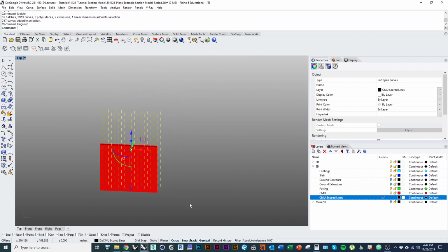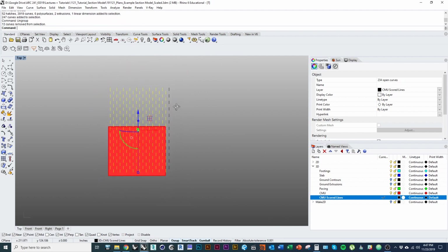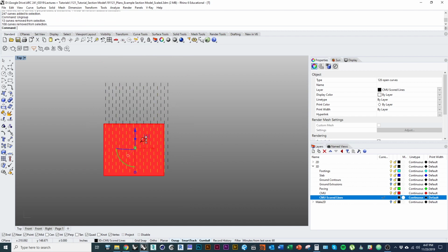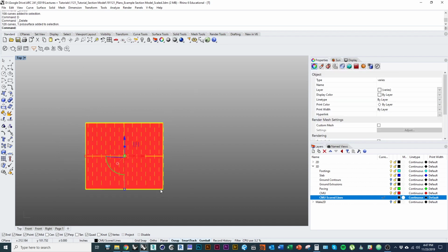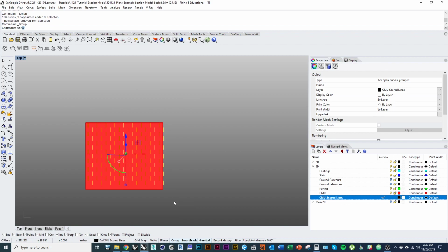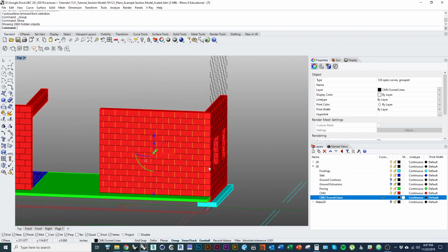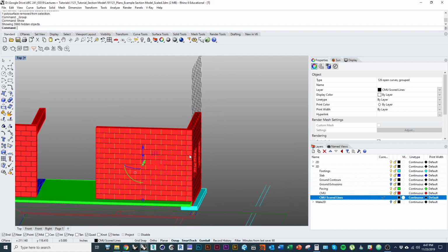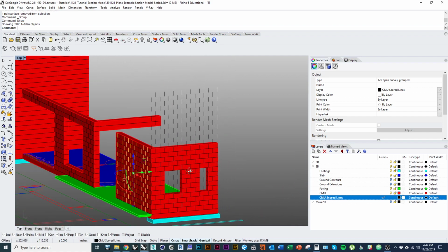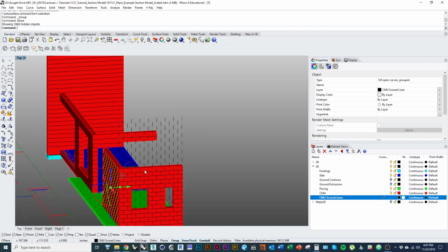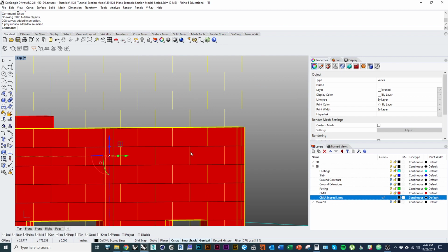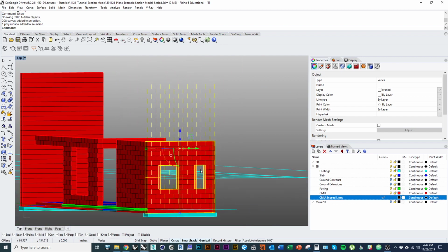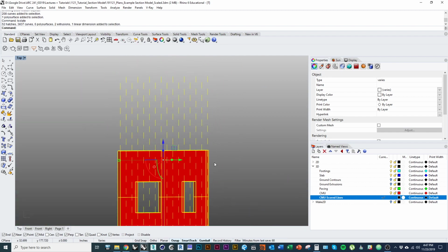And I should also point out, I'm only drawing these lines on one side of the wall. The reason being, when you laser cut, you're really only going to laser cut on one side of the wall. So it really doesn't make a whole lot of sense to cut these walls as 2 layers, so I'm just going to leave them as 1, and then contour, or I'm sorry, score the coursing in on the side that makes sense for the model.